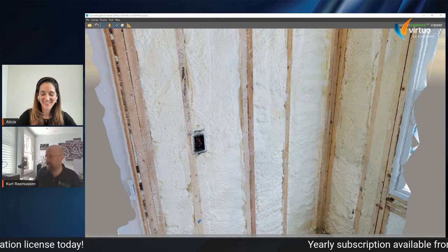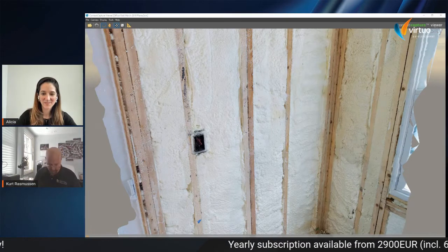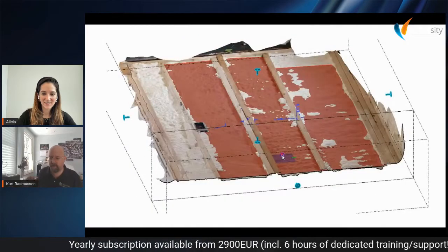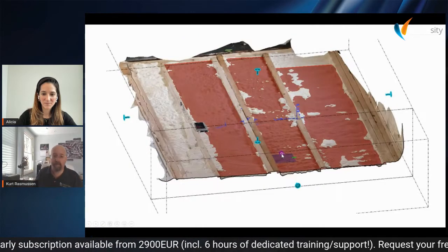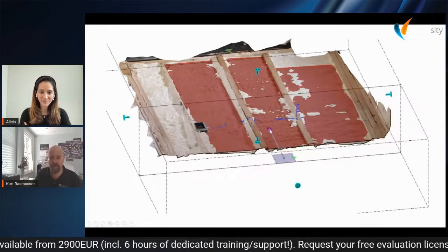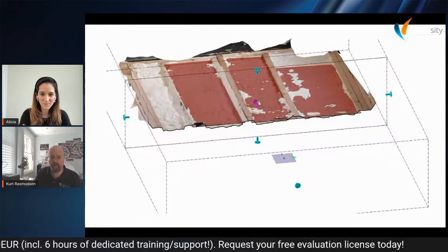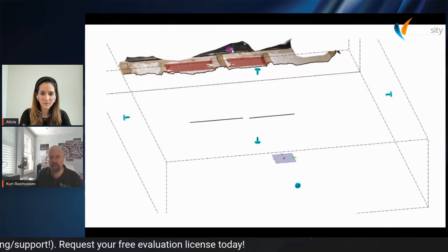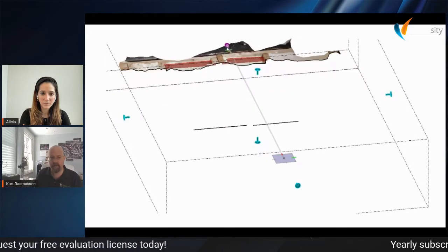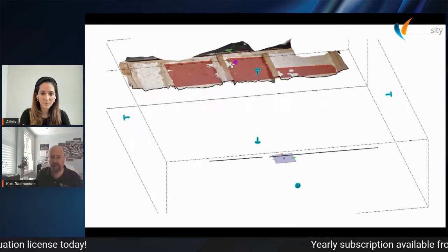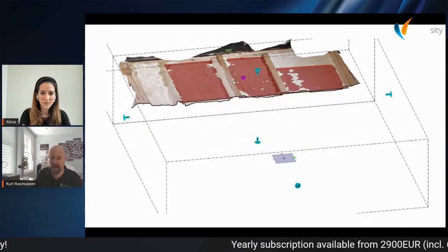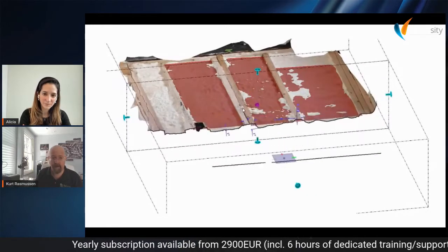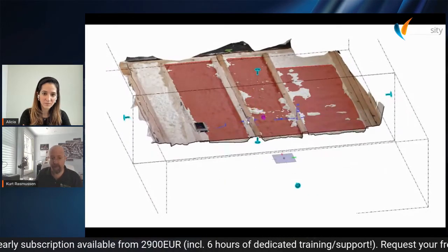So I threw together just a quick little PowerPoint, nothing beautiful. But why did I do this? Well, let's take a look, and we see here when I have a cross section of it, I'm moving through, and what we're seeing is that red plane there is really what an R21 insulation should look like. It should be at that level. So technically, I would expect it to be right above that red where I don't see any red. So like the left bay there, there's enough in there.